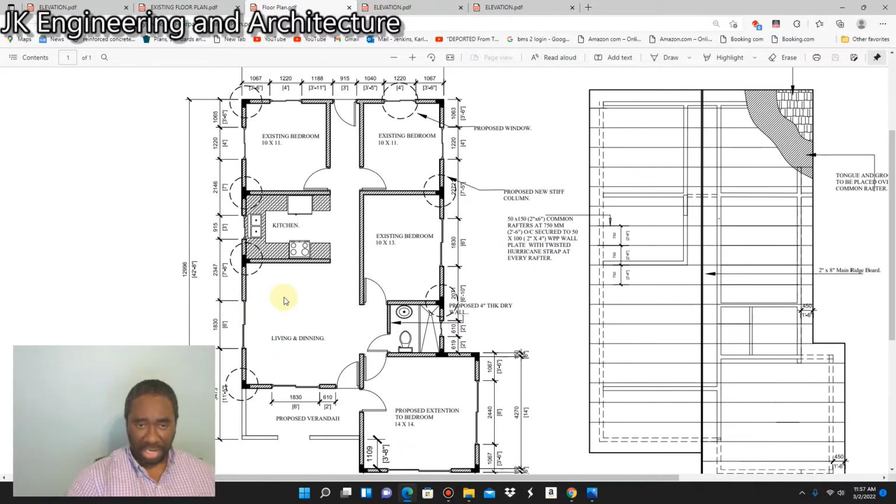So the scope of this project is just to extend the front room. We're going to take the existing roof off. We're going to lift the existing floor to, I think, 2 feet above street level. So we're going to take the levels from the street, measure 2 feet up that grade peg, transfer it inside the building, and lift the floor height 2 feet, and then lift the ceiling 2 feet. So we're going to remove the roof, strengthen the corners, and totally renovate, putting in brand new tiles, painting, and all that.